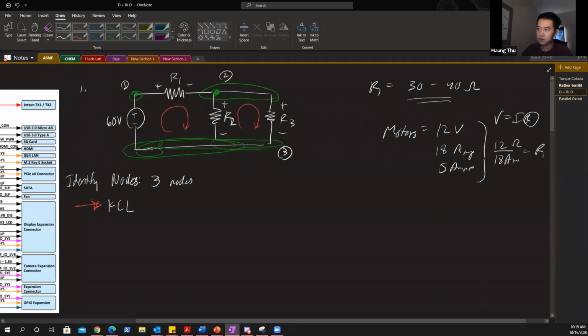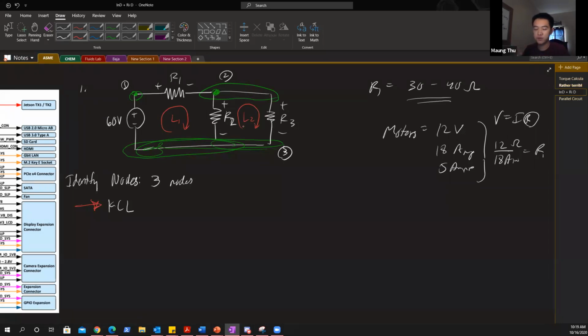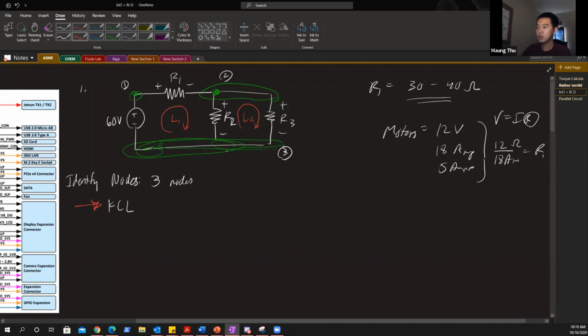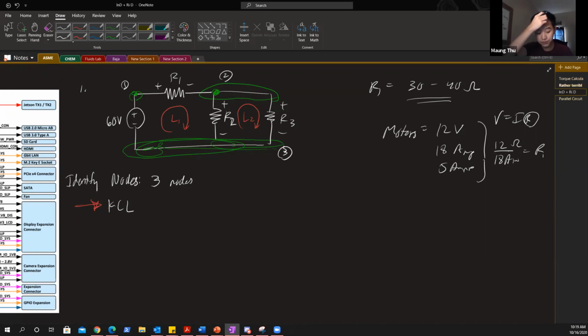One important thing when you do this analysis, with loop 1, loop 2, is that if you're gonna make this one clockwise, make the other boxes that you see also clockwise. Do not change direction in loop 2. It doesn't work. Okay, this is a method. There's no logic behind it. It's just a type of method that helps you solve the problem efficiently, if you will. Okay, you're gonna see this right now. You can see how Kirchhoff's current law works. So let's get into it.